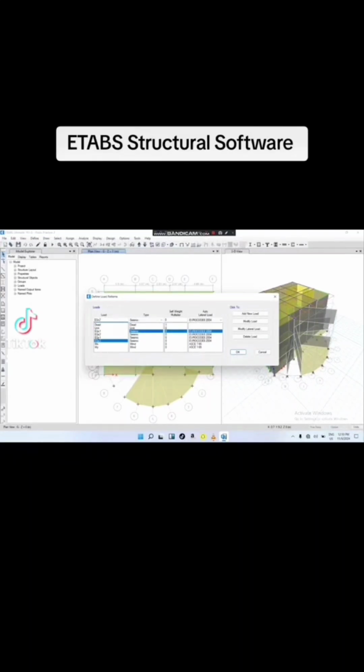The dead load factor will be 1, the rest will be 0. So in the name you will change the name, you will put EQ X1 like this.